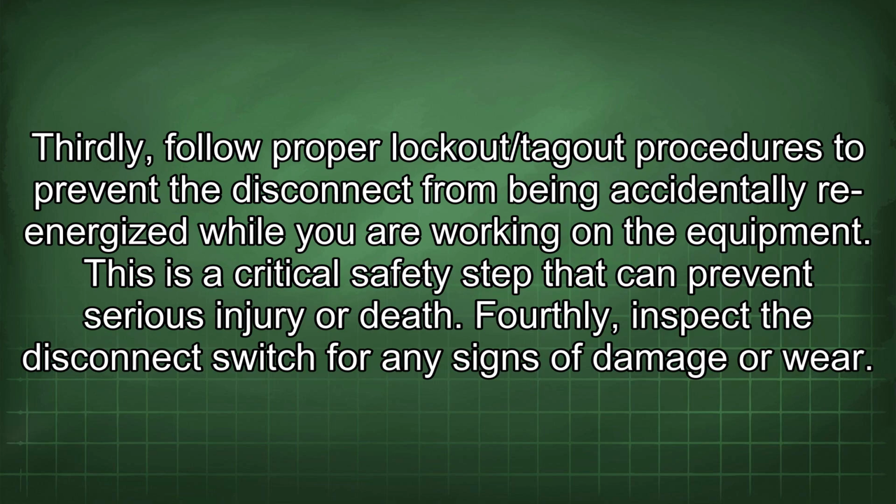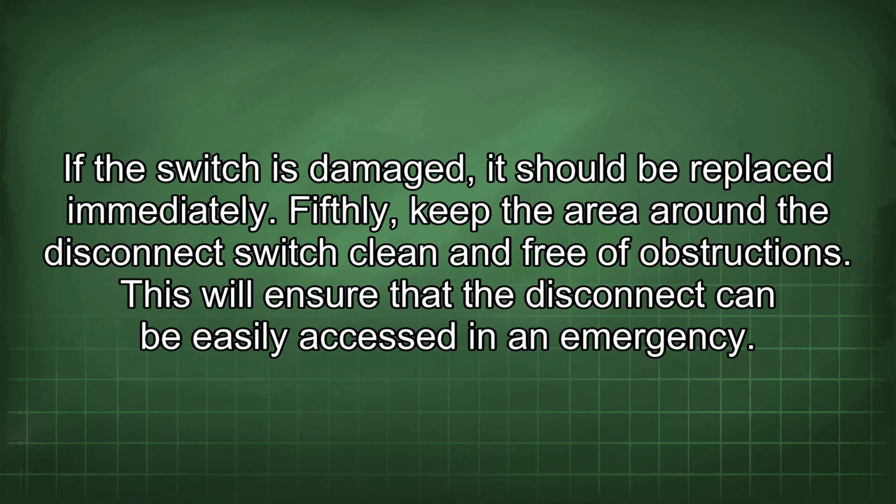Fourthly, inspect the disconnect switch for any signs of damage or wear. If the switch is damaged, it should be replaced immediately. Fifthly, keep the area around the disconnect switch clean and free of obstructions. This will ensure that the disconnect can be easily accessed in an emergency.